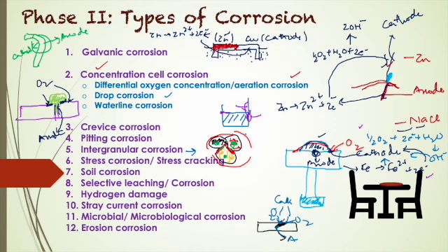So in that case, although both zinc and copper go into the solution from these alloys, only zinc ions remain in solution and copper is redeposited back onto these tubes. This is because zinc is quite reactive, whereas copper is nobler, if you remember the galvanic series. Hence dezincification proceeds continuously.